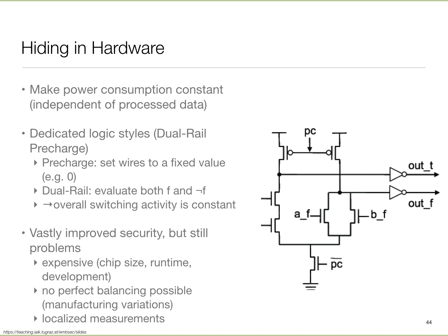The issue out here is that they are expensive. What you are really doing is paying with more silicon area. The other challenge is that even though they do all of this, there are still minor variations. Things are not entirely symmetric, so there is still some residual dependence upon the data value which can be exploited. But in any case, there's a long history of using these for crypto accelerators, so that you make the hardware implementations of the crypto more secure.